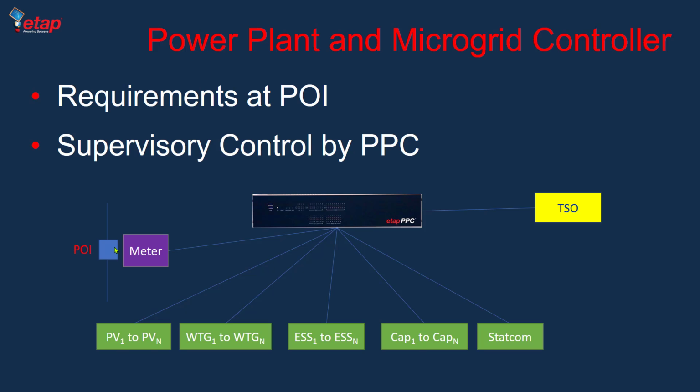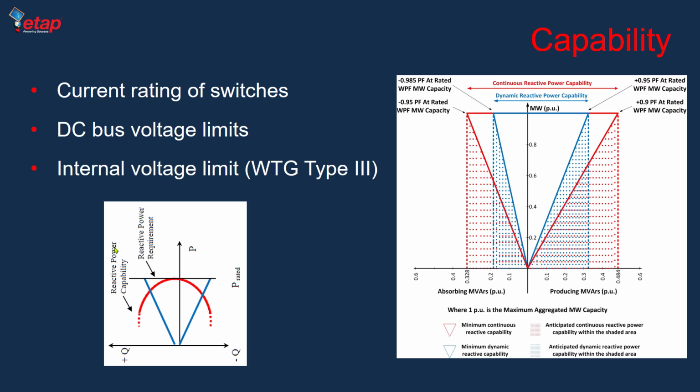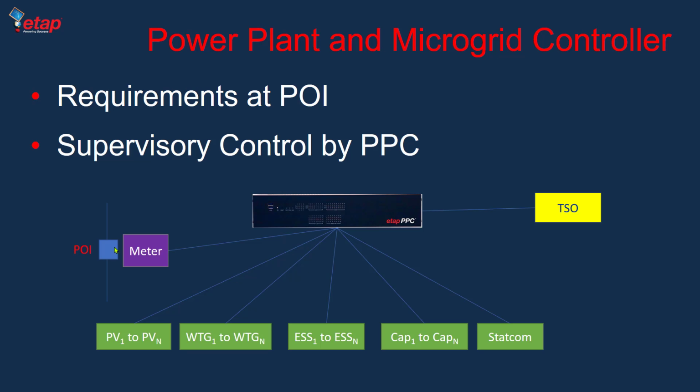And when we do the modeling of an inverter in a plant or in a microgrid, it's very important to also model the power plant controller or microgrid controller. Sometimes certain functionalities, like the volt-var compensation that we showed, rather than being done at the inverter level, are done at the plant level. Again, it all comes down to the expectation in terms of timings. If things are at the milliseconds level, typically they're done at the primary controller of the IBRs. But things at the seconds and minutes level are all done at the power plant controller level.